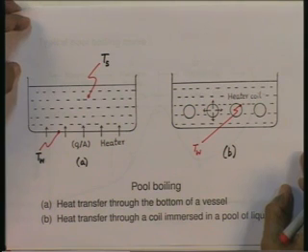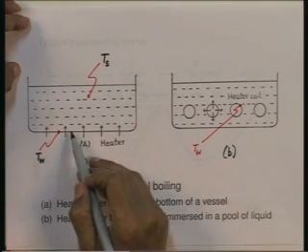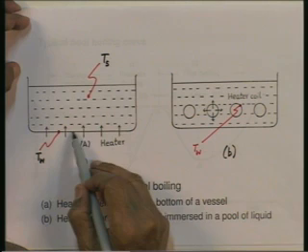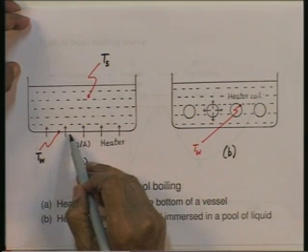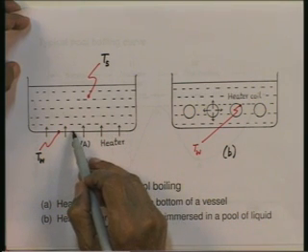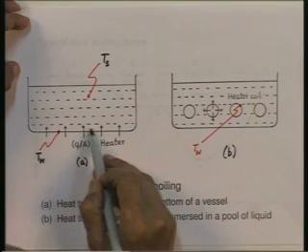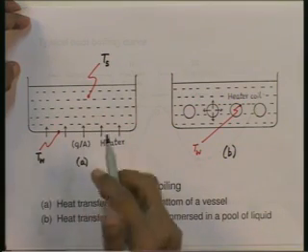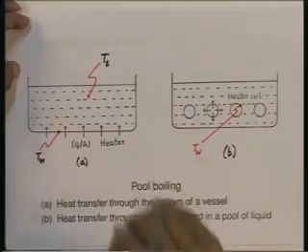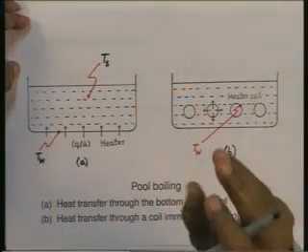In the nucleate boiling region, if one keeps looking at this heated surface at which heat is being supplied, one observes vapor bubbles forming at the surface. Vapor bubbles form at particular points on the surface. The vapor bubble increases in size. After it increases to a certain size, under the effect of buoyancy, it separates from the surface and goes to the top.